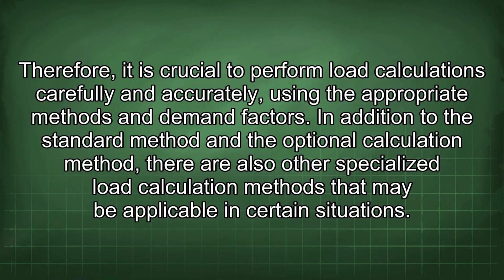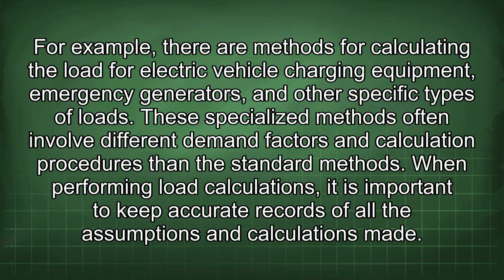In addition to the standard method and the optional calculation method, there are also other specialized load calculation methods that may be applicable in certain situations. For example, there are methods for calculating the load for electric vehicle charging equipment, emergency generators, and other specific types of loads. These specialized methods often involve different demand factors and calculation procedures than the standard methods.